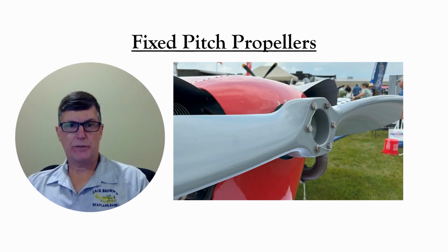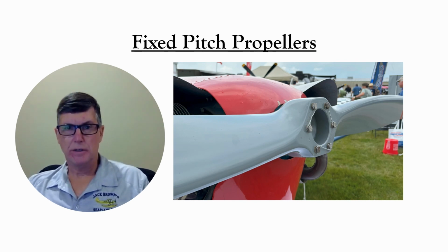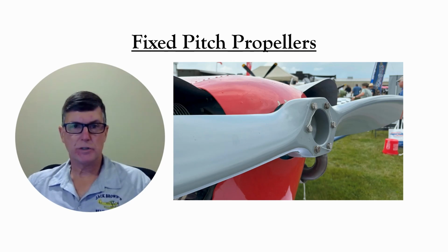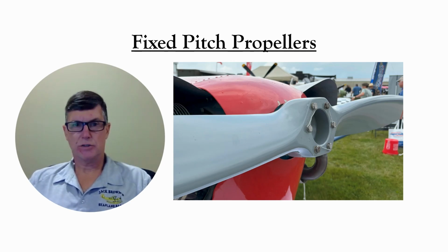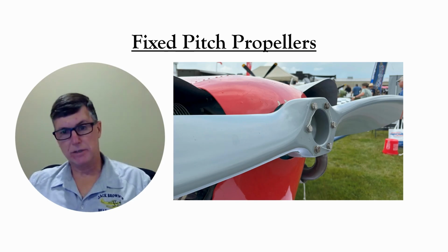However, a propeller that's optimized for climb airspeed will not have enough of an angle of attack at cruise speed to generate a high thrust force unless the engine's turning very fast, and engines usually have limits on how fast they're allowed to turn.